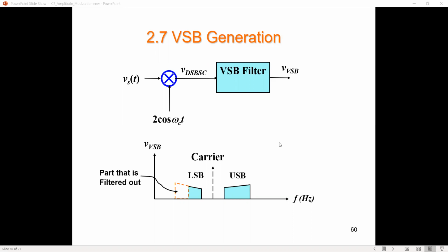If the question wants you to generate this type of signal, then for double sideband you need a bandpass filter tuned at FC, and you must make sure it also covers FC plus minus FM. If it's single sideband, your bandpass filter bandwidth is only FM, not 2 FM.